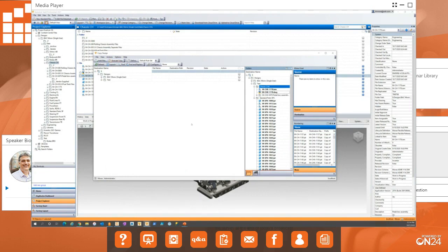So what I could also do though is go to the numbering panel here, and I can set my values for my prefix, make sure that's set to none. But what I want to do is come up here to options and look at my numbering schemes. Notice that even though I have a numbering scheme defined in Vault, it's not showing up in the copy design. I have to go to configure, and you can see that I have this BAC Mono X. It's not shown. So I want to show that, and let's go ahead and make it default as well.